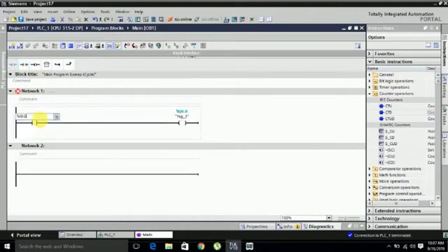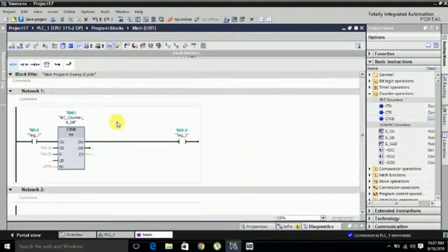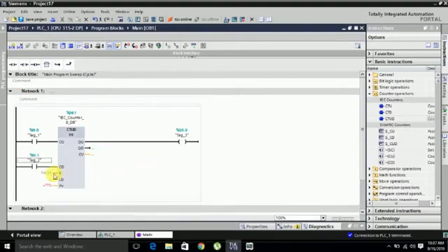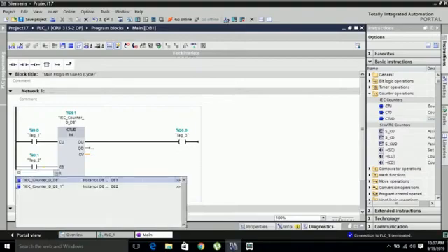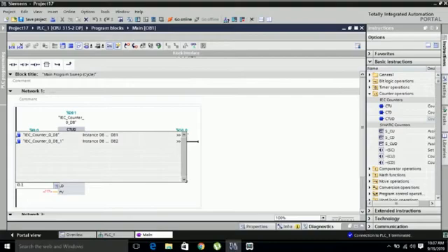So now we will discuss the counter up down. Same thing, you can select it. Here you see counter up. When I enable it, it will count up. Counter down, when I use this one, it will count downward and reduce your counter value. Reset, when I use this, it will reset to its original value of 0. Load, as you see in counter down, can put your PV value into the counter value.